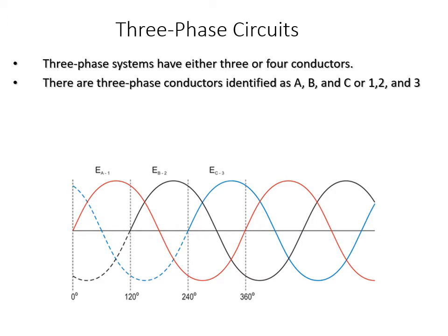Here in Canada, we typically use red, black, and blue for our 3 phases. There are other exceptions and other applications where the colors do signify a certain specific application, such as emergency backup systems, which you may find in a hospital. So for the most part, I'll be looking at A, B, and C, or 1, 2, and 3, and red, black, and blue in that order.